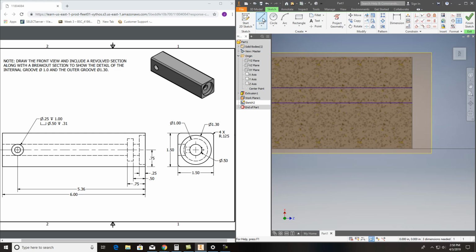And then I want to go off this outside line here, and I'm just going to roughly draw this in, and we can add more to it here in just a moment. We'll do our dimensions, but it's going to come in like that. Actually, that needs to come all the way down, so I want to extend it over as well. It's right there. Trim, get rid of that piece there. We don't need that anymore. And then I need to dimension that, so I hit there to here, and that is 1.3, so it'll be 1.3 divided by 2.